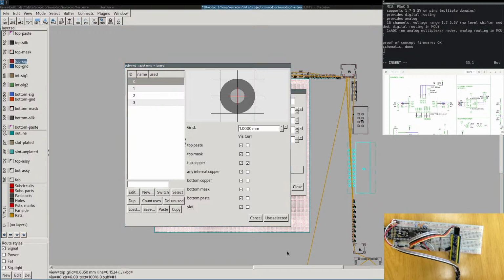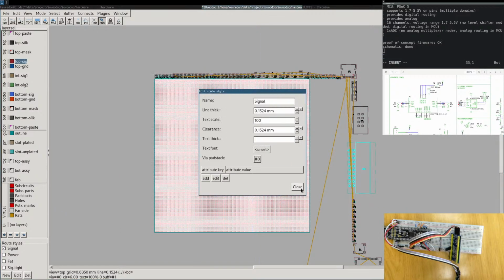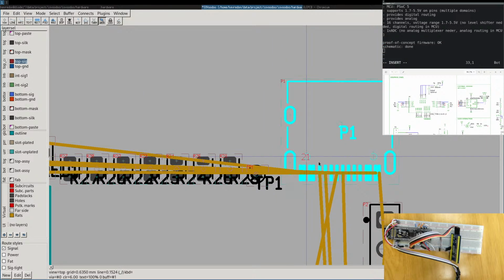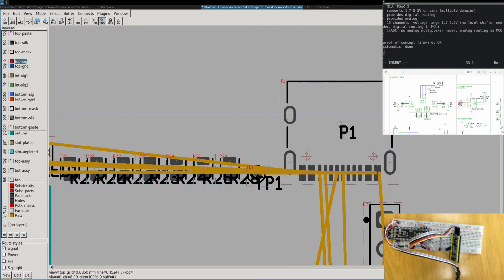Let me explain quickly. So let's cancel this. The footprints are called subcircuits because they're really mostly a drawing, but in a small format. You can think of it as a board layout, but just for one part. This is why it's called a subcircuit. Within the subcircuit, you have elements, mostly the pins where you connect.